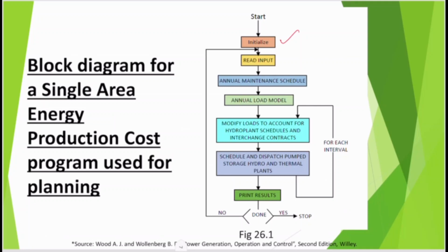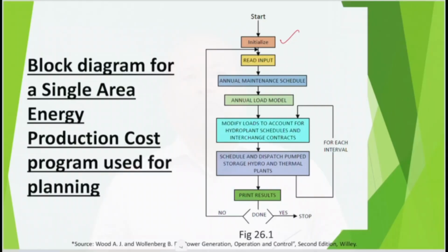Because you need to have the water model, the rain model, the hydropower output model, then the gas model, coal model, load model, and maintenance schedule of thermal power plants and hydropower plants, and then you get an overall solution. Okay, this is how my next 1 year is going to be with the existing infrastructure or the generation available to me.